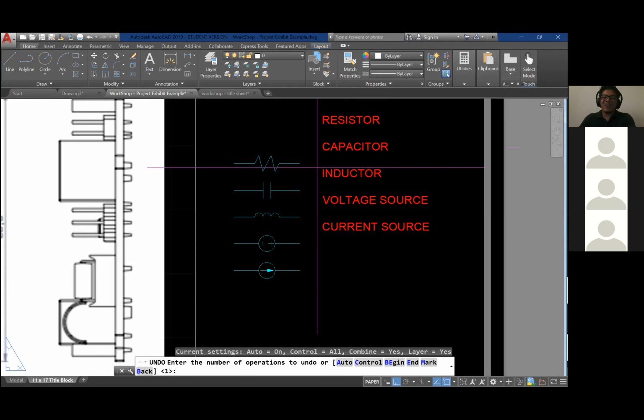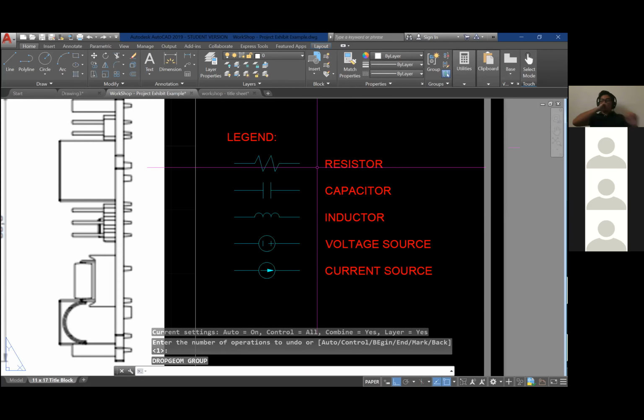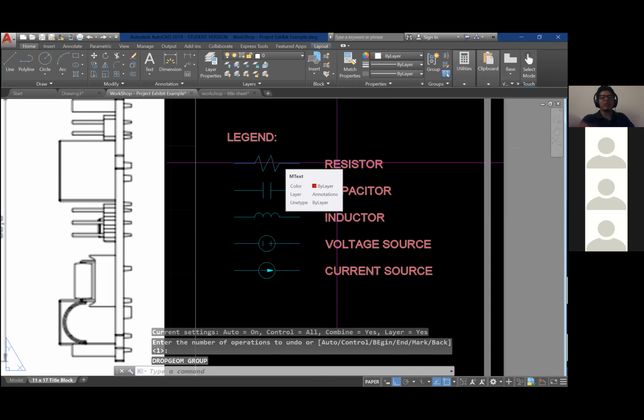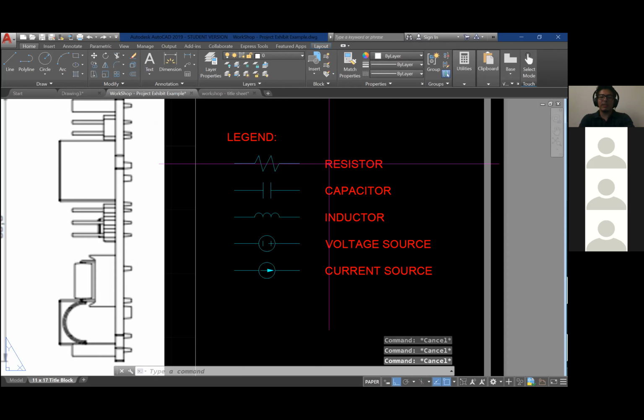I did that a lot to the topographical maps, and that put a bunch of their stuff out of place on a project. I got in trouble for that because I didn't know that happened, and I got yelled at for that and a few other things. These are all little mistakes. You saw I moved it and it looked out of place, but when you're dealing with background objects that you don't pay attention to, if you move it, you're not going to notice it. That's why these are things you have to look out for.